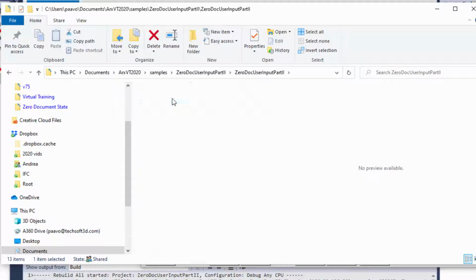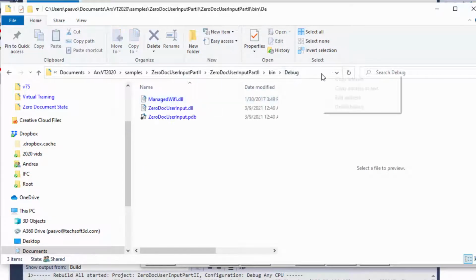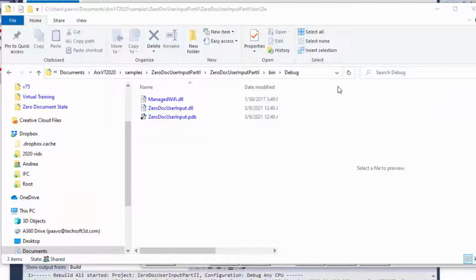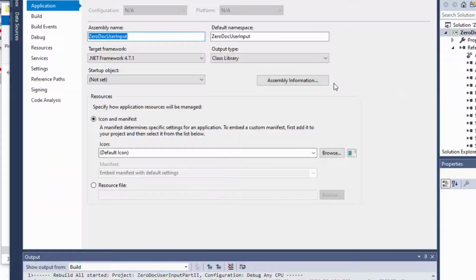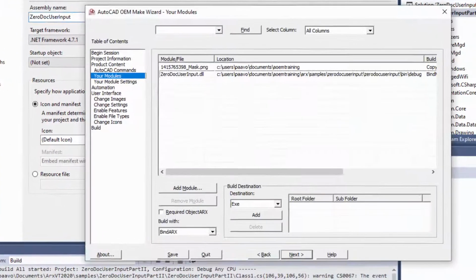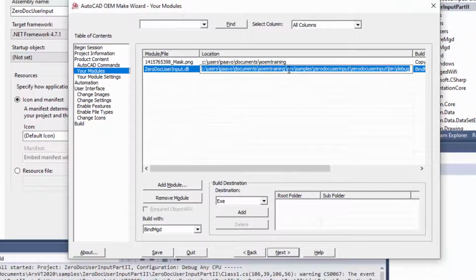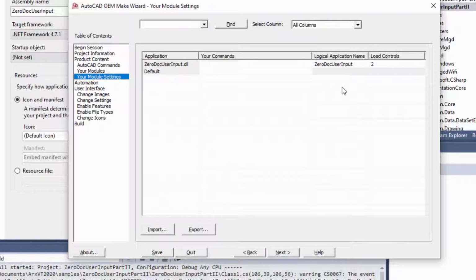This is handy because if we remove the previous DLL and add the new one, we will have to supply the module settings data again, either by typing them in again or read them from a location where we have stored them. This will save you some time when switching from debug to release on 20, 50 or 100 runtimes.